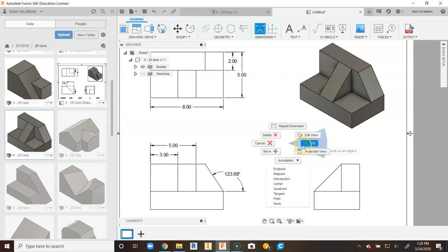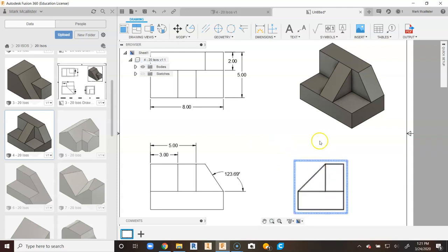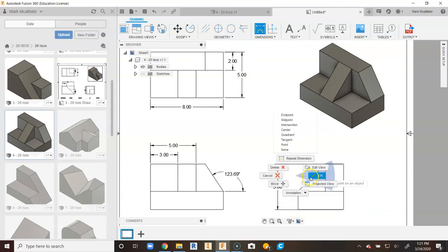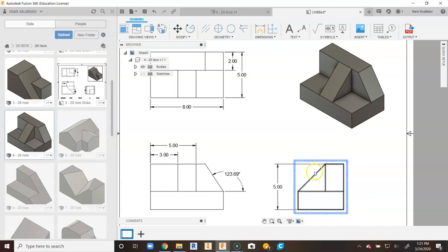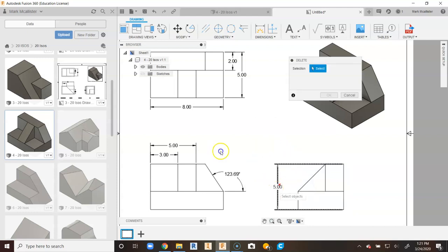We want to make sure that we maintain adjacency between our views when we dimension, but in this specific case I'm going to choose to go non-adjacent only because of what I've kind of been saying. Again, whatever you choose to do is just generally fine, but this line looks like it's continuous from this object and can make the viewer automatically think maybe it's not part of it. Even though the line weight is greater a lot of times in your actual drawing, sometimes I like to make sure that things are completely and totally clean.